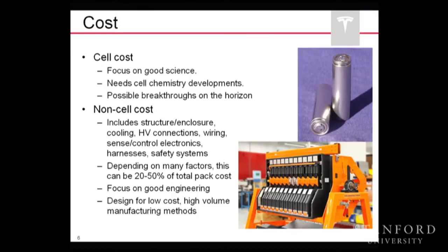So when you take a bunch of these cells and put them together, lithium ion cells need to be monitored. You want to make sure they're balanced. Our battery pack in the Model S, for instance, is close to 400 volts. It has almost 100 bricks, we call them, in series to stack up to give you that 400 volts. You want to make sure that none of those little bricks get out of whack, that for some reason, maybe one of the cells has a little bit of a short circuit in it and is slowly draining off the power in that one brick, for all those little cells in parallel. You've got to monitor the voltage on each one of those bricks. So if you've got 100 bricks, then you're going to need 100 voltage sensors keeping track of all that stuff.